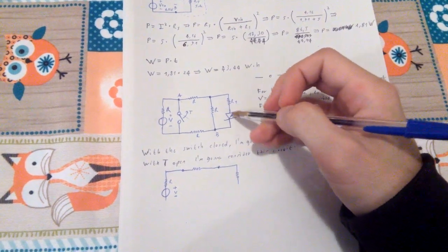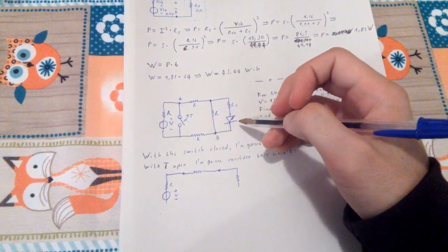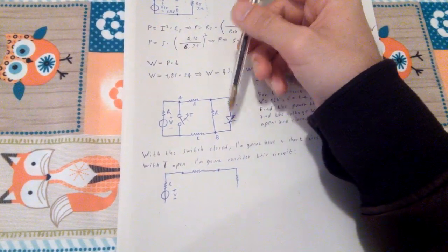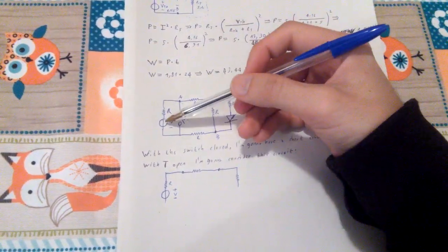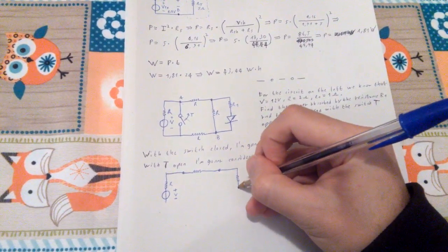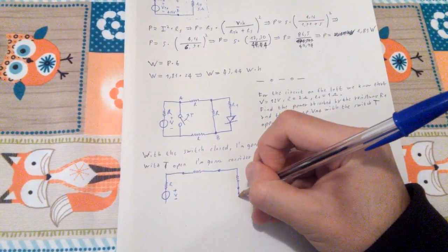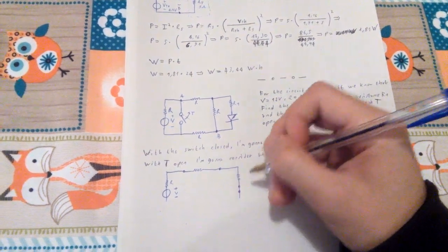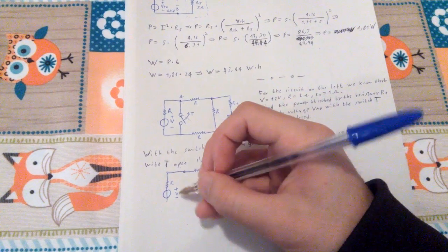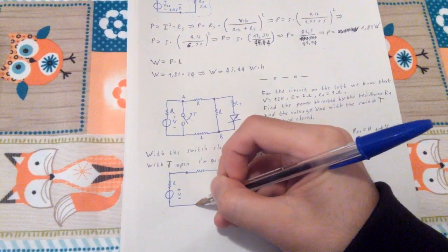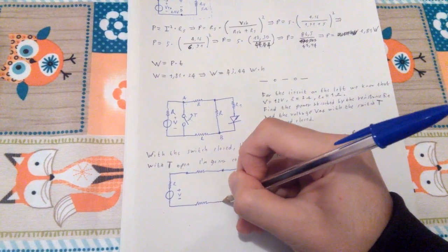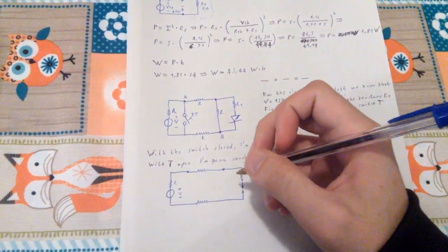Then there is nothing going to be here because the diode is polarized in this direction, so it is going to allow the current to flow in this direction, but the current is actually flowing in the other direction. So I'm just going to short circuit it like so, just to remember that there was a diode once, but it's not going to matter. And at the bottom, I'm going to have a resistance going all the way to here.